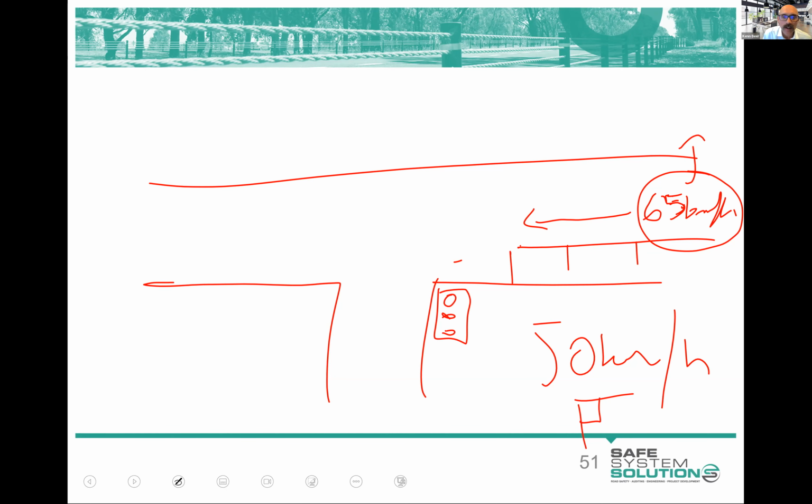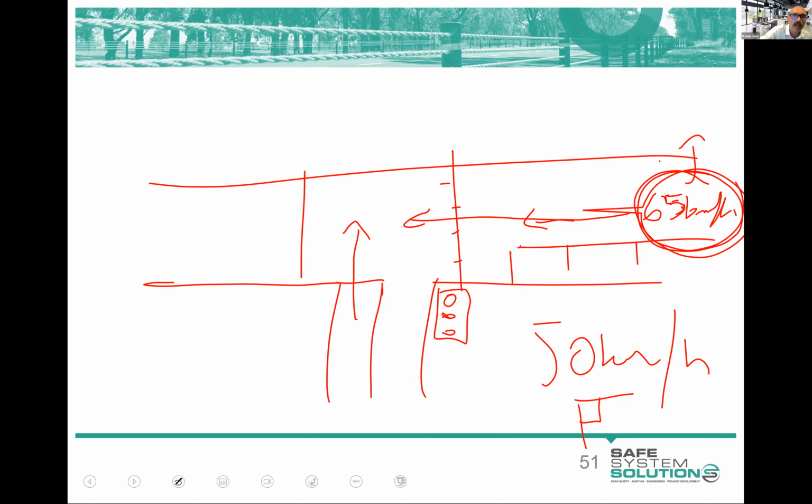Because it's much less likely that anybody does this, but this driver can come out here and then this driver can still run the red light at speed. So we've significantly reduced the likelihood of this, but it's still there at that same speed, at that same energy. Again, signals with a raised platform, or if we were in an environment where we had an operating speed that was quite low anyway, then signals are fine. They're in the primary category.